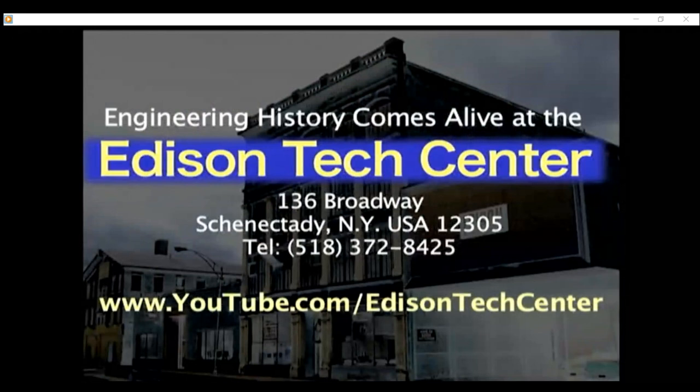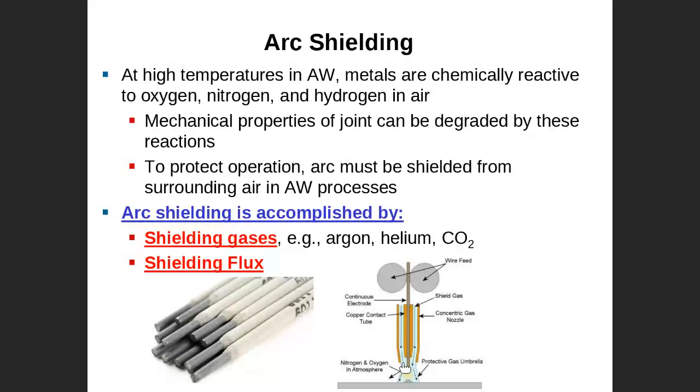Shielding means protecting. The weld will react with the environment. You must shield. We shield by either flux or gas. The only two ways to shield: flux or gas. Gas like here, this is a continuous welding, meaning the wire here is continuous. This is a consumable, for example, consumable electrode or non-consumable electrode.